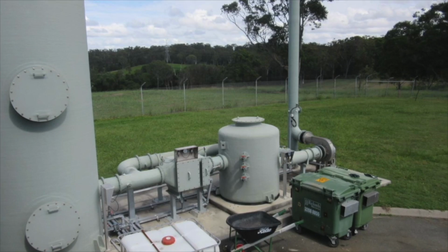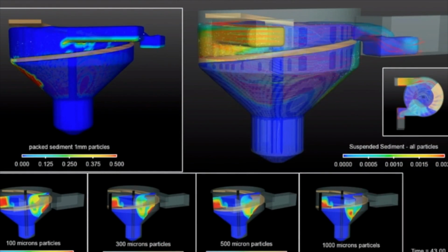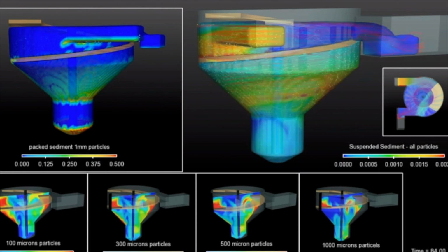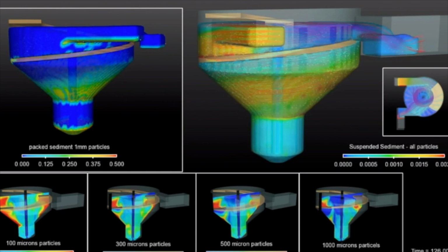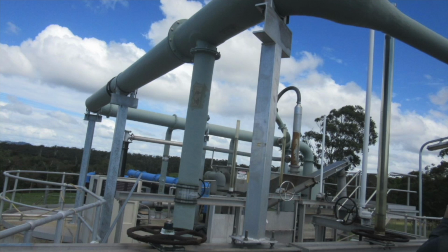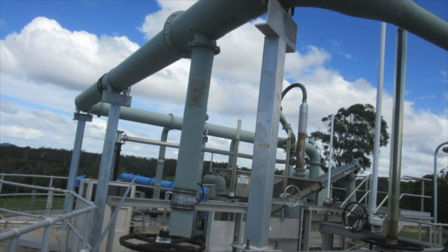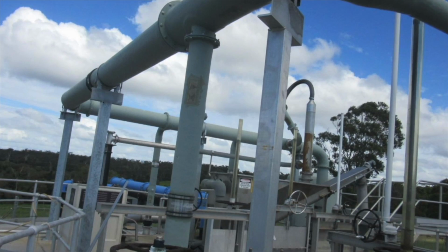After the water leaves the screening stage, it goes through a vortex grit removal system in order to settle down the finer sand particles and smaller impurities. This is achieved by pumping the water into a specially designed conical tank that triggers vortex movement of the liquid, pushing the grit to the walls of the tank so it can settle down by the force of gravity into a special bin. The inlet works is also equipped with a hydrogen sulfide (H2S) scrubbing and ventilation system that alleviates malodorous gas above human breathing level.